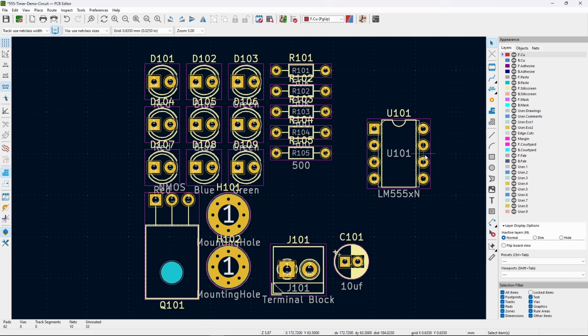So we see these holes here. These are our through holes that we're going to be using to solder the timer to the board. And that's obviously quite important. We have to make sure that that doesn't overlap with anything because that's a physical part of the board. Then also we have this silk screen. That's this cream colored layer, and that's just a not electrically important part. It's just for humans to see, look at the board and figure out what's what.